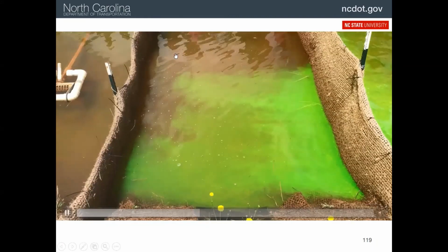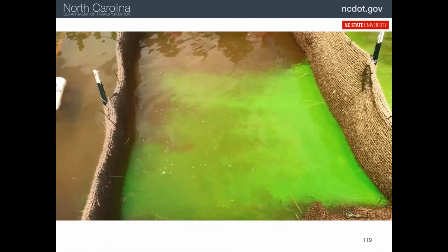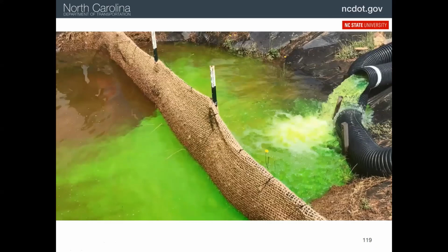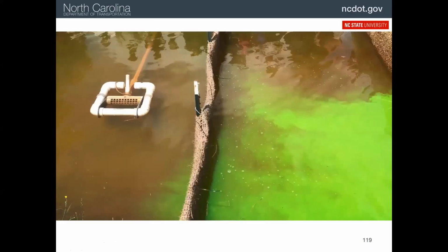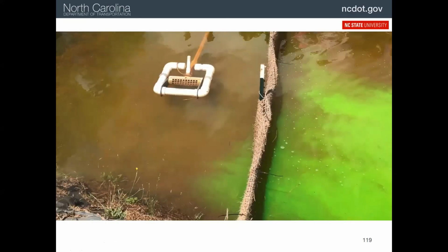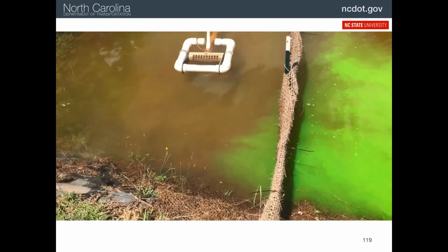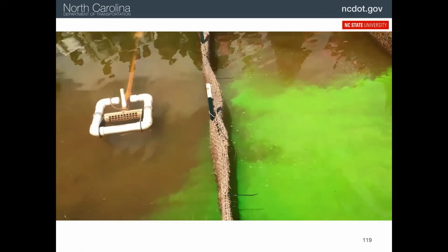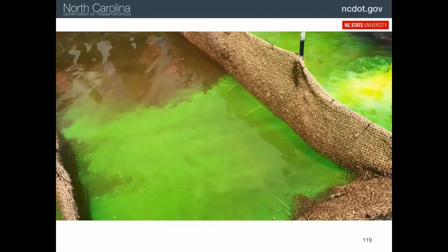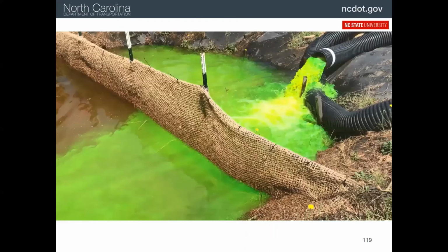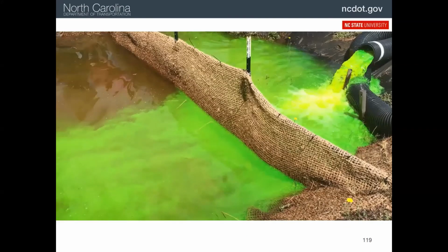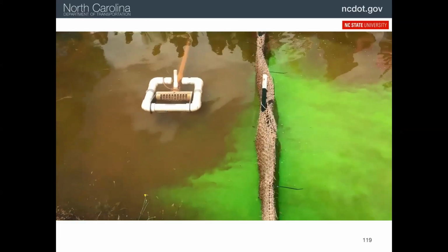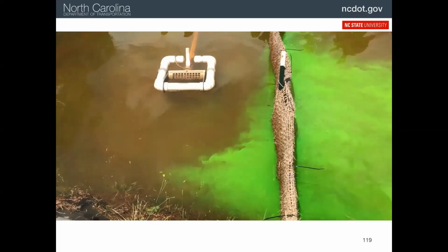And then we get through the second baffle, and then you really see that effect. Okay, you see we're spreading the flow and taking out the turbulence, and then look here. Now you can see those fingers and how there's just no turbulence at all. And that's perfect. So between the removal of the turbulence and spreading the flow and taking water off the top of the water column with the skimmer, we can get these basins to take literally 99% of the sediment out of the water coming in.